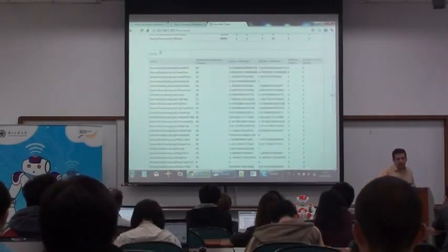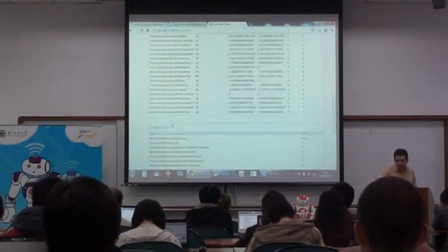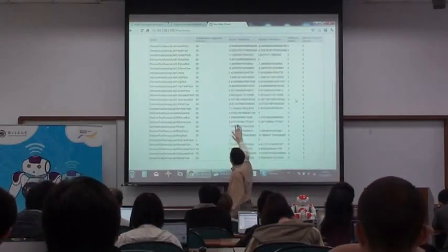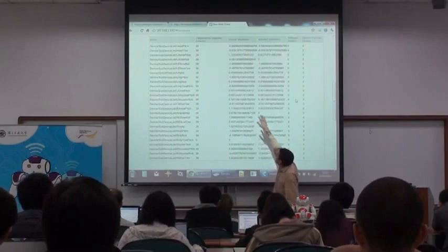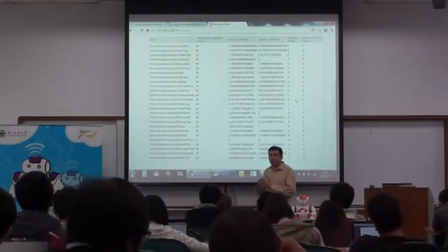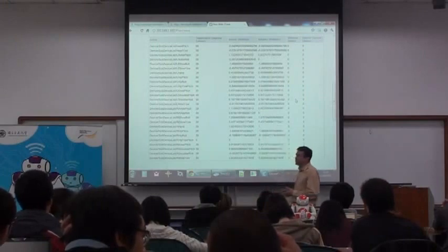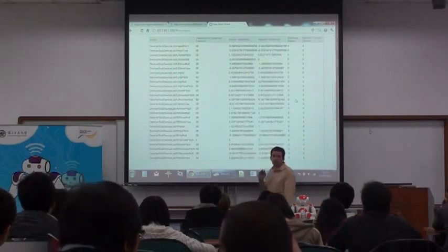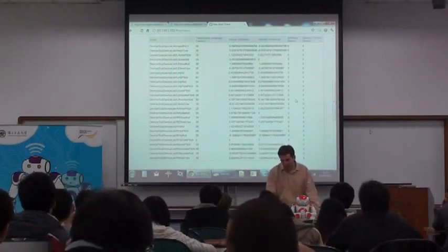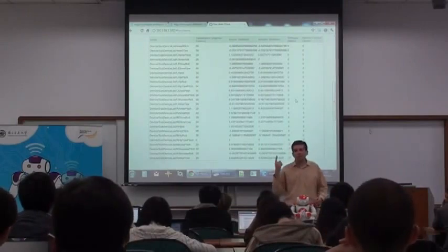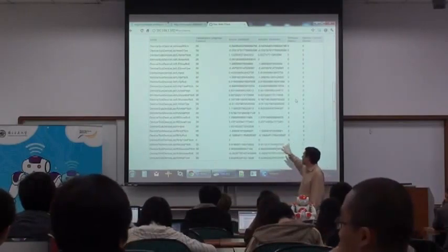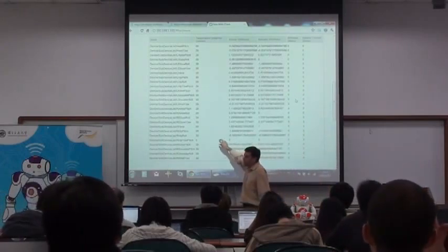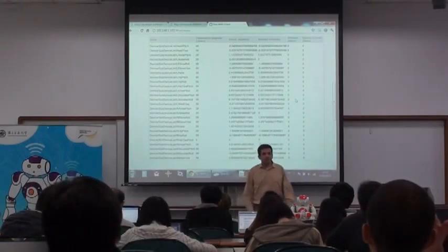The second table lists all the joints, so all the motors. For each motor you have the temperature and the two angles: one after the gearbox and one directly on the motor. These two values may be a little different for the bottom joints, but on the top there's only one MRE, like I told you, so the values are the same. You also have the stiffness ratio and the electric current in amperes, but here there is no stiffness, everything is zero.